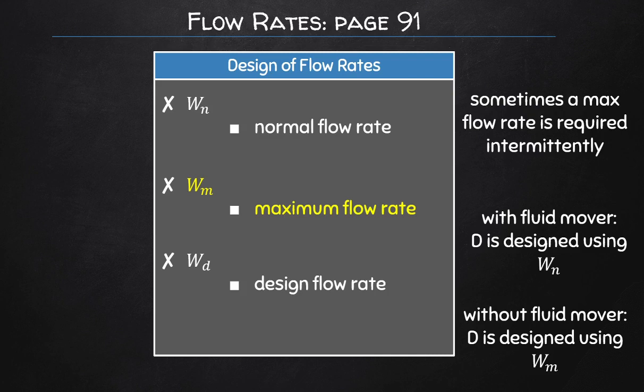What you would then do is push up neutralization liquor, which would be at a certain flow rate, just to neutralize the liquor that has formed inside the digester, and then once the digestion is complete, you would reach a maximum flow rate out of the digester as you're discharging the contents.